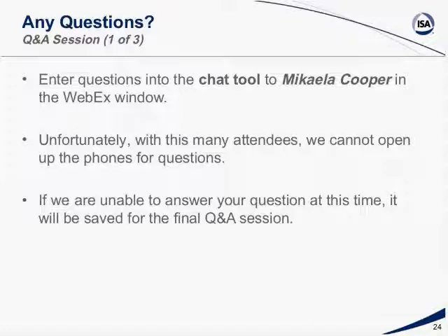When you shut the plant down, and at the places I've been to, we've had a lot of discussion about this because, oh my gosh, you're shutting the plant down, that should be the highest priority. And what it always ends up being is no priority. You don't have an alarm because there's nothing for the operator to do. The plant's shut down. And trust me, you shut a plant down, everybody's going to know. I mean, it's just the way it is.